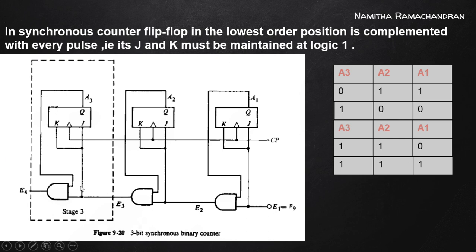Okay. So again this current value of A3 is 1 and E3 is 0. 0 and 1 is 0. So after this increment operation, it does not generate any carry out. The carry out value after this increment operation is again 0 here. So this is the circuit diagram for a 3-bit synchronous counter. This type of synchronous counter is used for implementing an increment operation over accumulator register content.